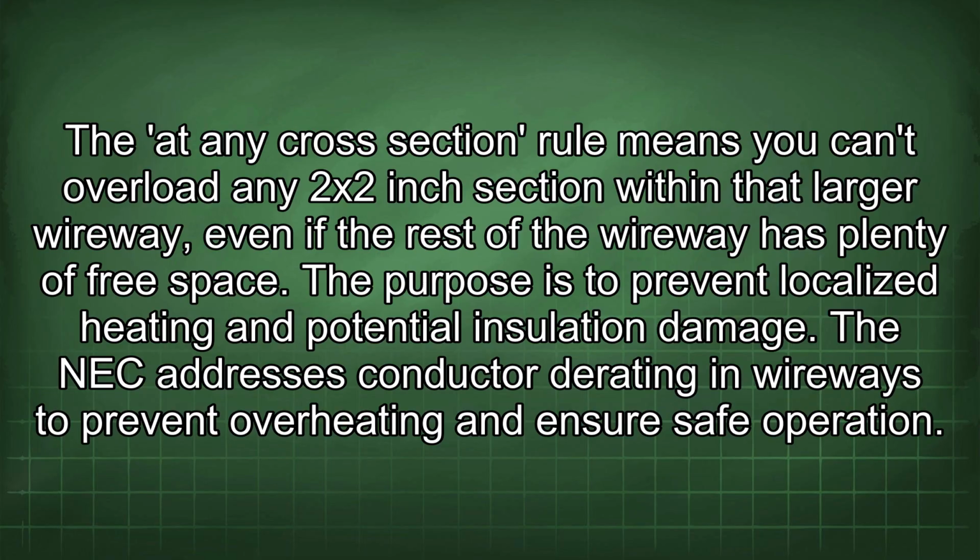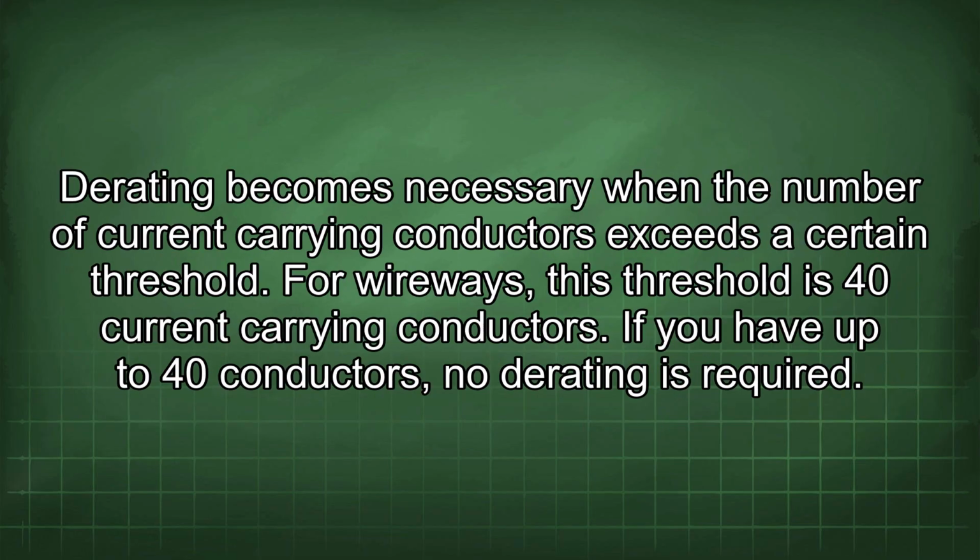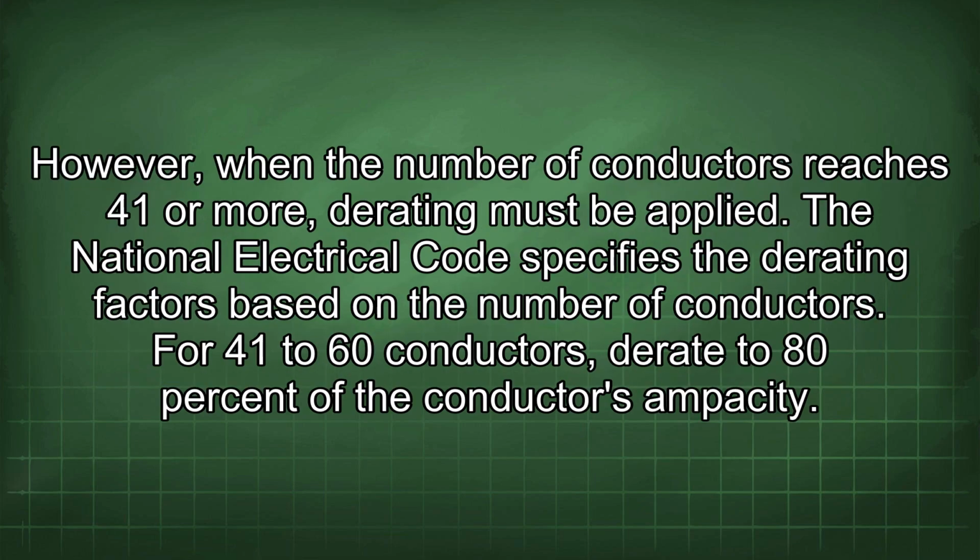The NEC addresses conductor derating in wireways to prevent overheating and ensure safe operation. Derating becomes necessary when the number of current-carrying conductors exceeds a certain threshold. For wireways, this threshold is 40 current-carrying conductors. If you have up to 40 conductors, no derating is required. However, when the number of conductors reaches 41 or more, derating must be applied.